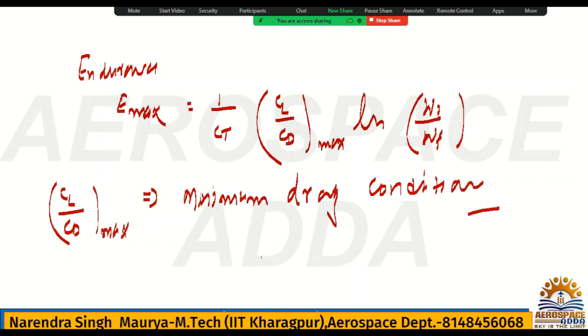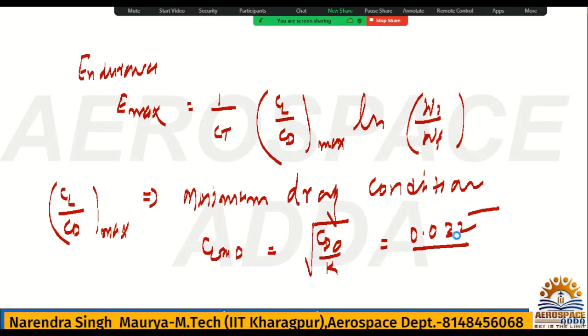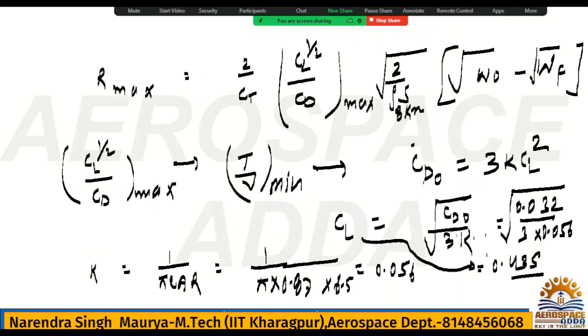So what is the CL at minimum drag? It is root of CD naught by K. What was the CD naught? CD naught is 0.032, divided by K. You had calculated K. What was the value? 0.056.